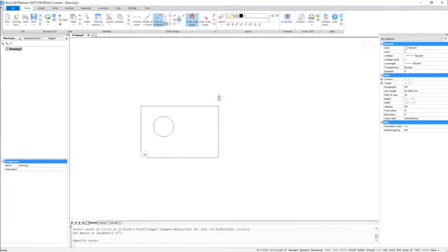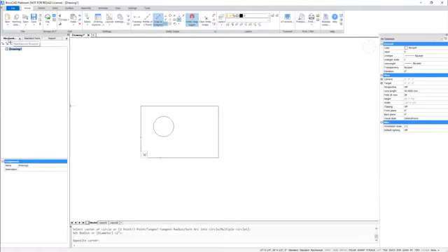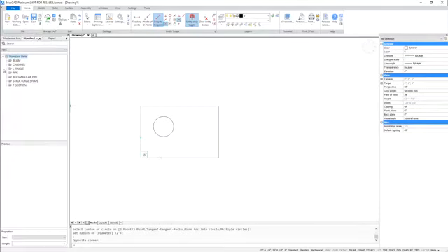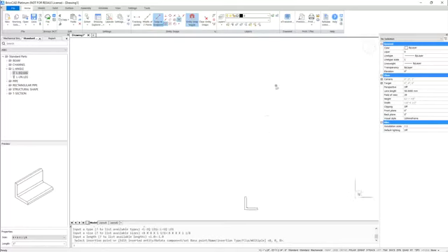And then if you go back to the workspaces, I could choose mechanical, and that displays a very different looking workspace. And here I've actually got a ribbon that's displayed by default, but again, you can customize these workspaces and the way all of this behaves and looks. But with the mechanical workspace, I've got these palettes over here, like the mechanical browser. I've got the standard parts. This even comes with a library of some standard parts that you can use. I could just take one of those and insert it in here. And that's a 3D part. So it does come with some standard libraries. And of course, you can create your own and add your own there.